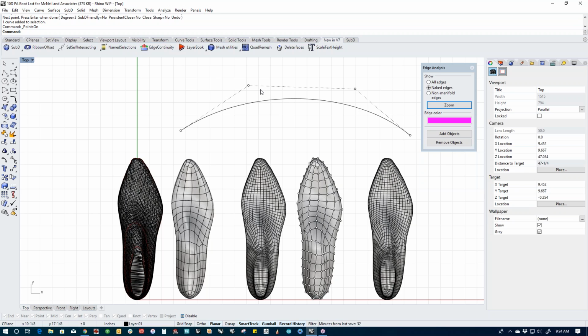So the connection between a quad mesh and a SubD, the control cage on a curve, is the same relationship. The quad mesh is the little dotted lines and the points. The SubD is the curve, right? So the two have a relationship similar to points and curves. Does that make sense? I don't see anybody running for the door yet, so I think I've still got you.